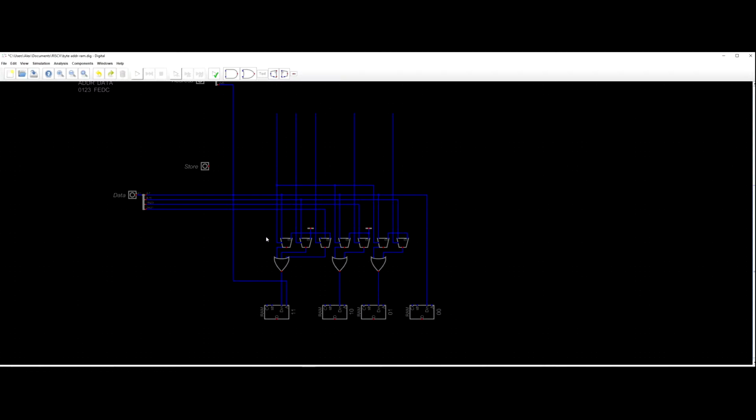I'm controlling the data going in. So I can write a byte of data to any of these. I can write the low byte there, and then the only thing that would be allowed to come into here is then the high byte.